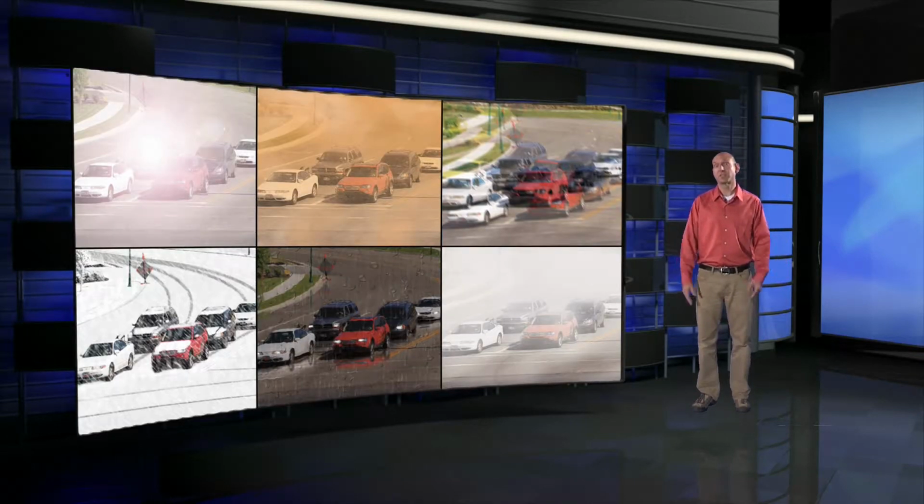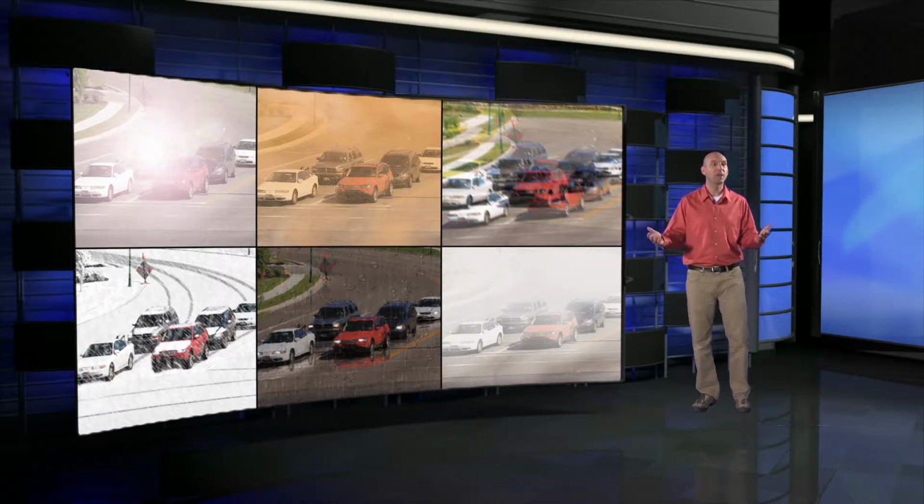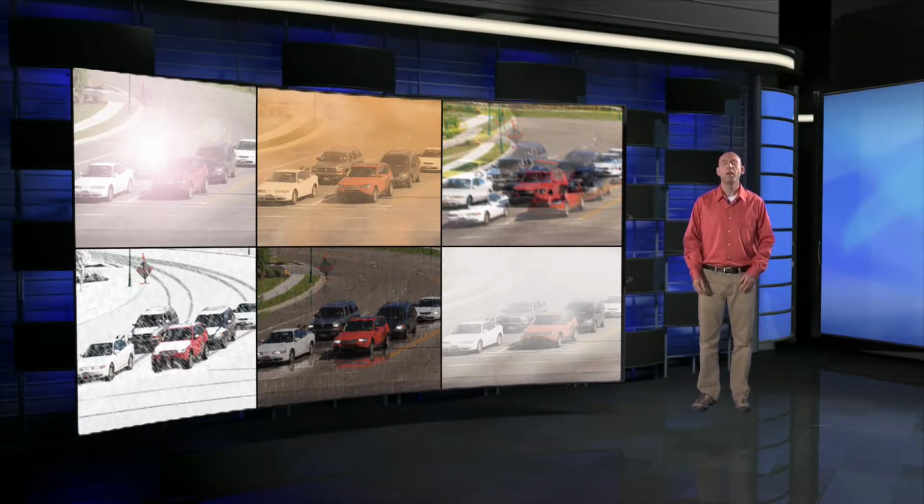The problems with video detection, however, are well known in the industry. There's problems with glare, with shadows, and changing lighting conditions. There's the cleaning that's required for the cameras themselves. There's problems with any kind of motion or vibration of the camera. And of course, weather conditions affect the quality of the video image that's produced and will affect the detection accuracies of the sensors. So in this presentation, I'll explain how these problems are overcome by radar and how radar is able to create an image just like video is. But first, I'd like to talk about the different types of radar that are used in the marketplace.